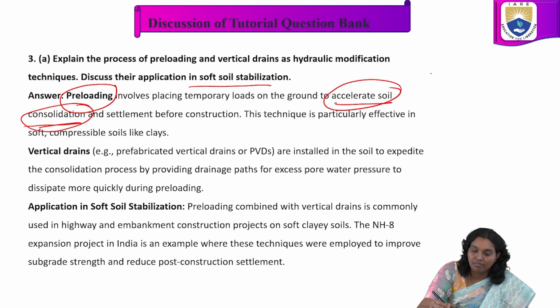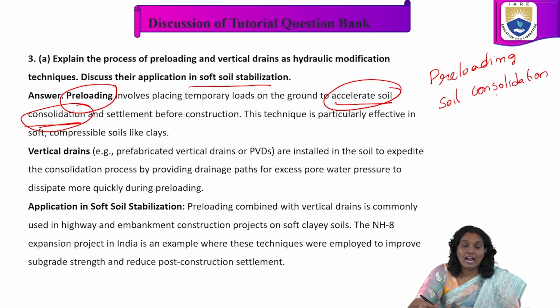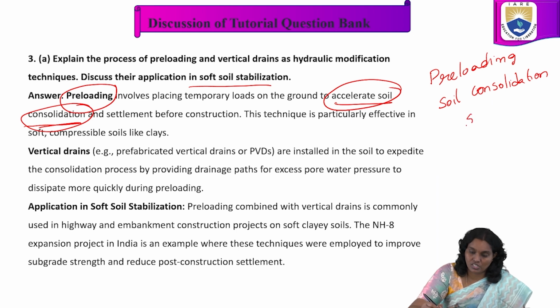Here we use the preloading technique for getting accelerated soil consolidation. Highlighting that property is very important. Consolidation and settlement before construction.